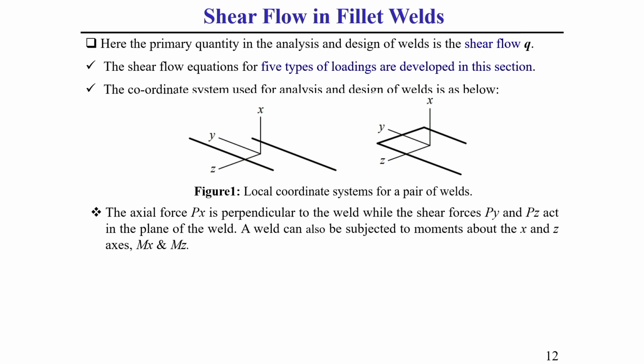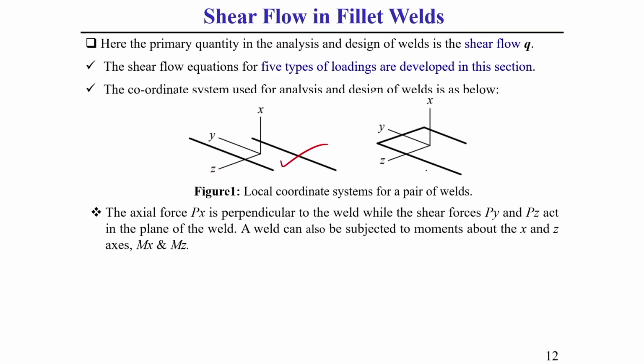Now, we will discuss, for a combined load, how to find the shear flow and related things in detail. First of all, we need to specify what our coordinate system should be. This is the coordinate system we will generally use for the resultant shear flow calculation. I will discuss in detail how to find it.